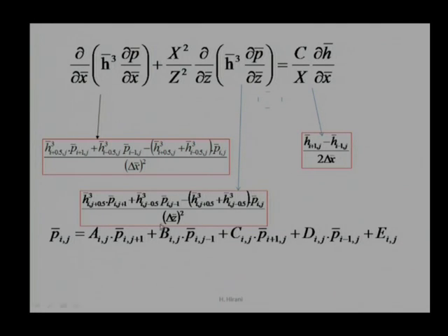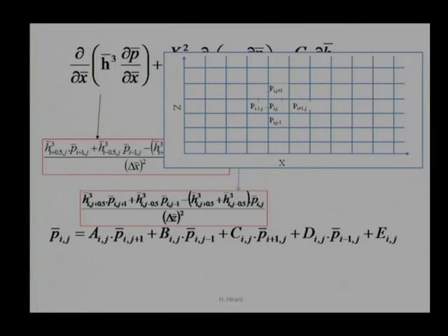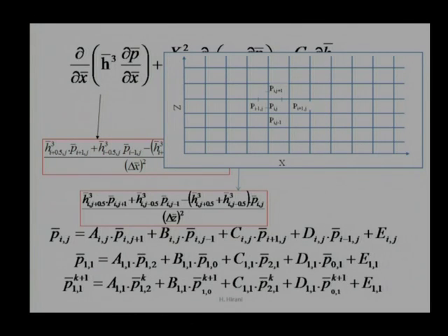However, the pressure will continuously change as per the iterations. It may increase if we are using the initial pressure as 0 pressure, as gauge pressure is 0, or the pressure is atmospheric pressure. Then we will slowly get more and more pressure at the node, and finally it will reach a saturation limit, and that saturation limit we name as the convergence limit. That was indicated in a previous lecture and is repeated over here.